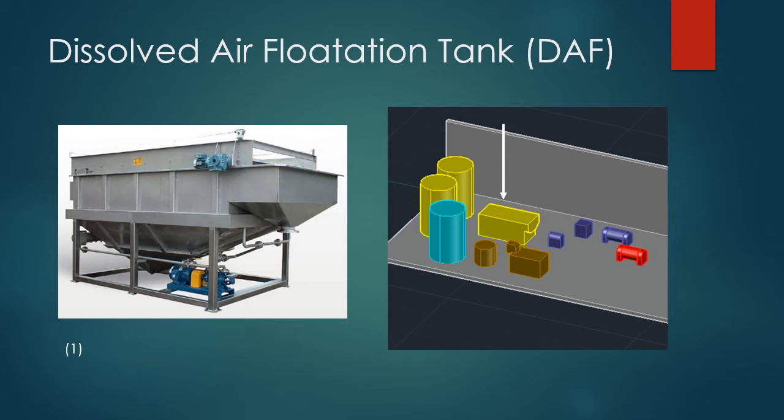This helps in two ways. First, to separate the brown grease, which will settle on the top first, then to separate the food solids, which will be taken from the bottom. The oil that comes off of the grease trap waste will be sent to the skimming tank, the brown tank located below the DAF in the model. The rest of the wet food solids that come out will be sent to the centrifuge.